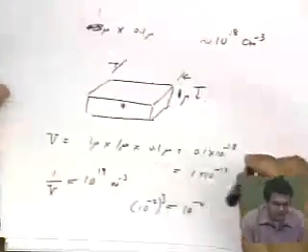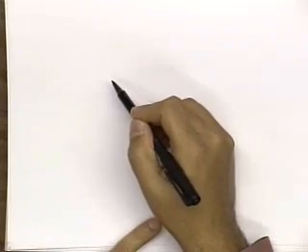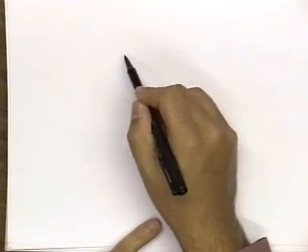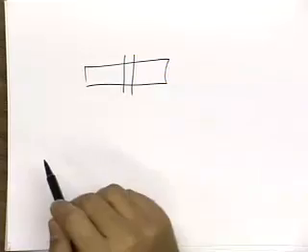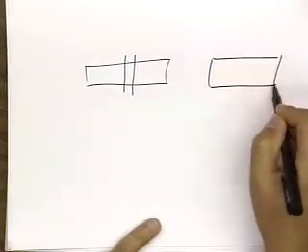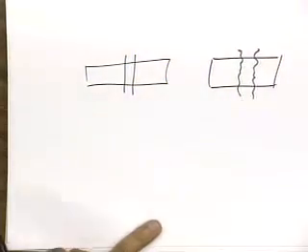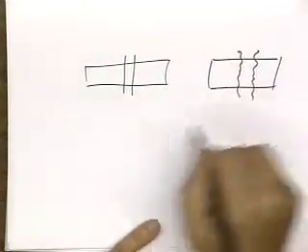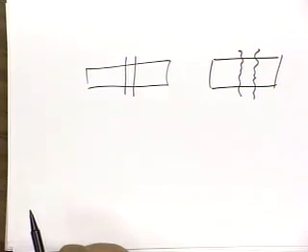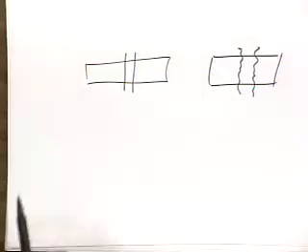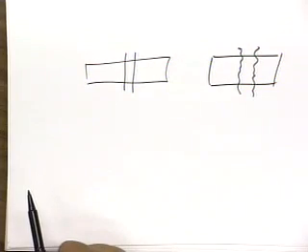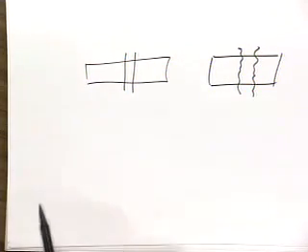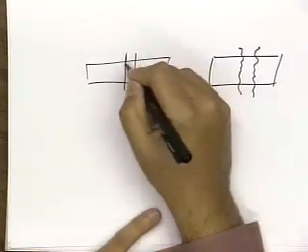But another thing that comes out is, as you make these dimensions smaller and smaller and I build a transistor, I may draw it like this, but what I actually get is something like this. So the roughness, the line edge roughness. As you make things smaller and approach nanoscale, these natural variations that occur in real structures really start to be important. Over here, for a long channel transistor, you don't even see it.